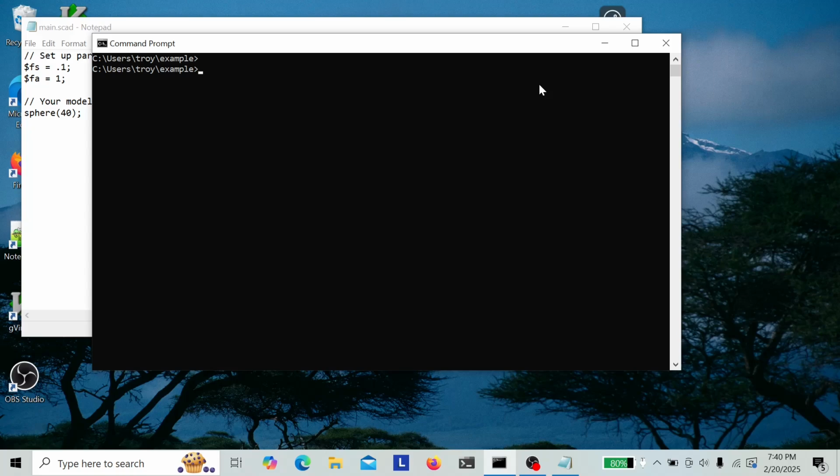And if I want to build this, I can just type 3dm build. So this will create an STL file. It's just going to be in the build directory, and I can list it. So if I do dir /b build, main.stl. C:\users\Troy\example>. main.stl. So another feature we have in 3DMake is that we can use AI to describe the model to you.